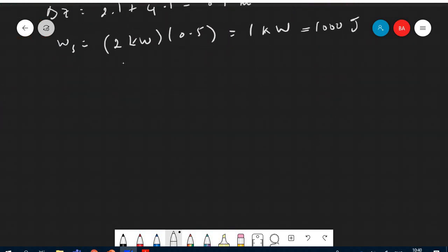So m dot is equal to, if you can just recall, u times A, which is the volumetric flow rate, multiplied by the density, which gives the mass flow rate. So this will be equal to 1600 kilogram per meter cubed, which is given to us, times u, and area is pi d square over 4.